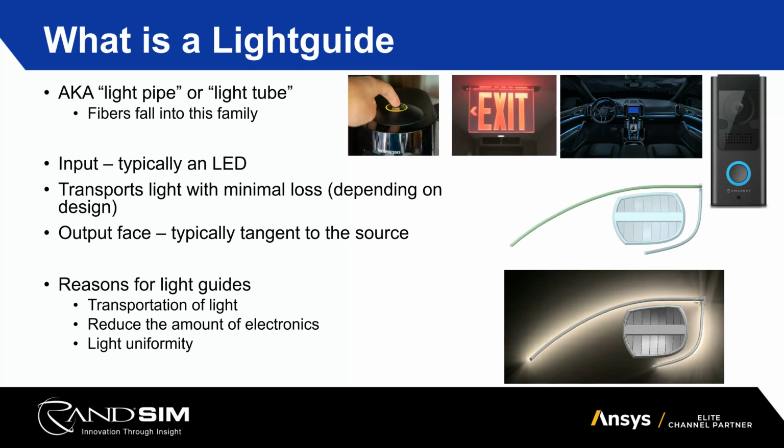Now, previous to people really using light guides a lot, it would be an array of LEDs. So it could be up to 12 LEDs with a sort of dispersive material on top to mix the light, so you didn't just see the strict LEDs. But it can get costly to have that many LEDs, and then on top of that, you have to pull more power, and you have to cool down the system way more.